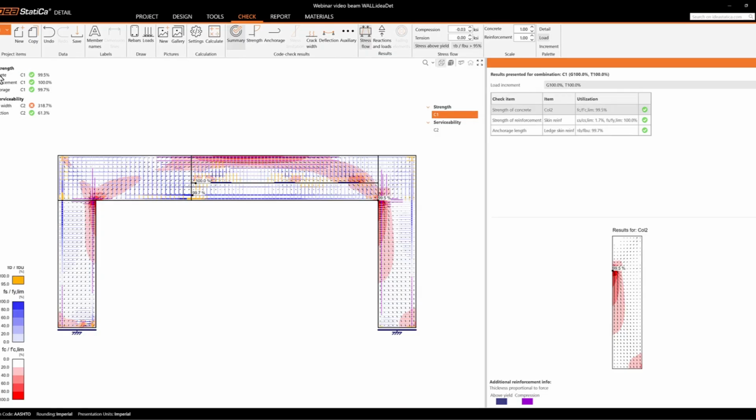For the strength combinations, we're going to look at 3 limit states: concrete, and reinforcement strength, and then the anchorage. The anchorage can be translated to what we know as development length, right? So if you design concrete, you know that you need to calculate this certain length, so you know that the steel reinforcement is well anchored to the concrete.